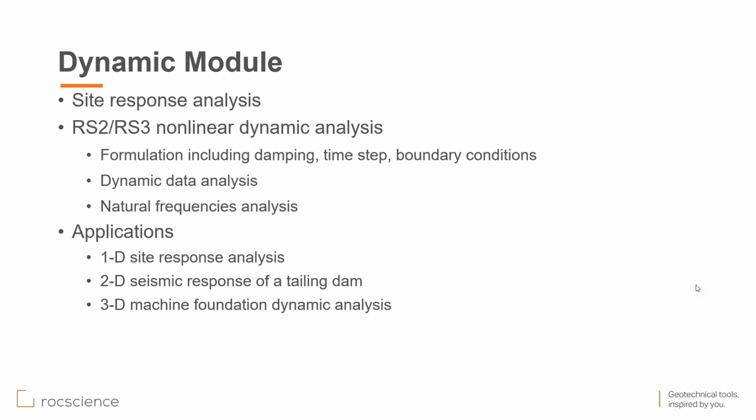So let's talk about this approach. In this approach, we have a constant shear stiffness for each pass of the time history. It means that, for example, initially we will assume an initial value for the shear stiffness, and then we run one pass through the time history with the constant shear modulus. After that, we get the peak shear strain here at gamma 2, and then we get the equivalent shear stiffness, a new one called G2 here.